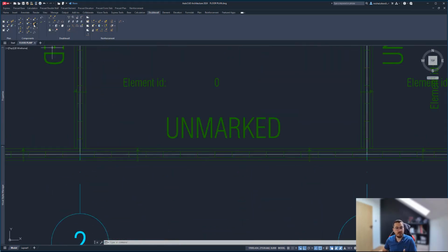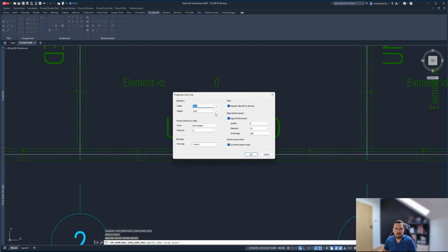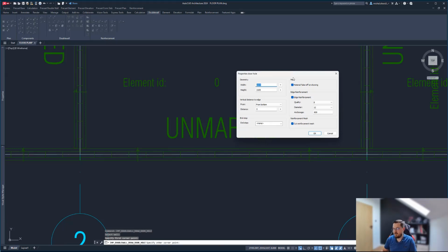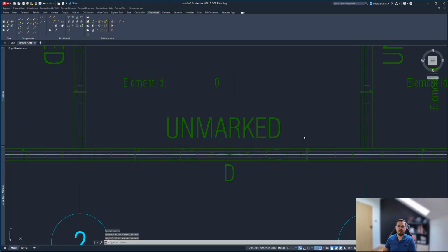What I will do is also create openings, because that might be of interest to you. There are a couple of different ways to create openings. There are rectangular openings, circular openings, window holes and door holes. I clicked on the door opening, I clicked on this wall, and I'll just start placing an opening of some dimension, because it doesn't matter what the dimension is on screen, since you can still fix it here. For example, make it 2000, right? That's good. I can specify the spacing and then the exact placement of that, if I need to add reinforcement, if I need to cut meshes inside that, and whatnot. If I want to add an end stop, I can add the small one, for example, or maybe 130 might be better, and let's accept that.